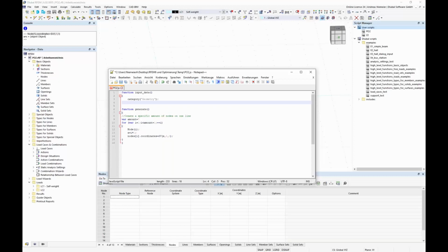Now, below this header, we want to specify a parameter. It's an integer parameter, which has some properties. It has a name, the name is amount of nodes. The next is the parameter internally encoded amount, which we use below. Then a unit should not be specified for this integer value. The starting value is, for example, 4 or 3. The unit type internally is unit, point none. The value should run from 3, should be increased by 1, and should be maximum 50, and the last two parameters should be true, so that I can use it.